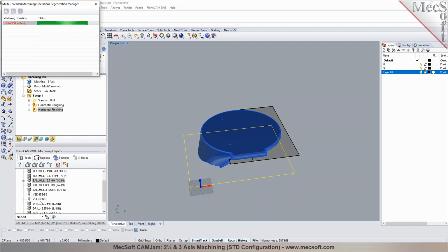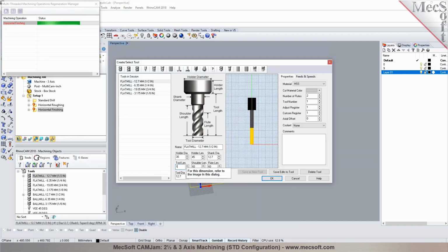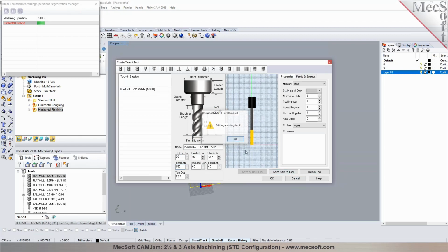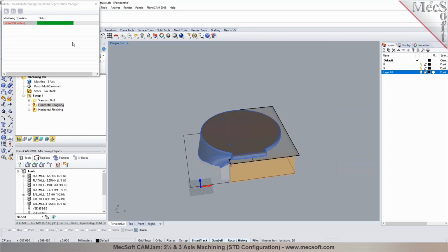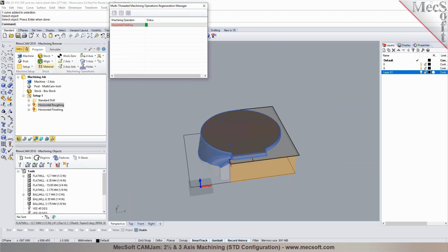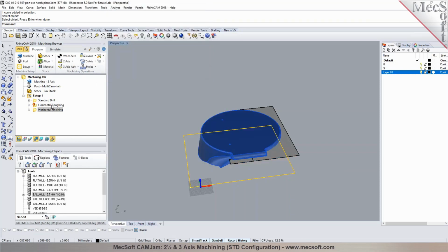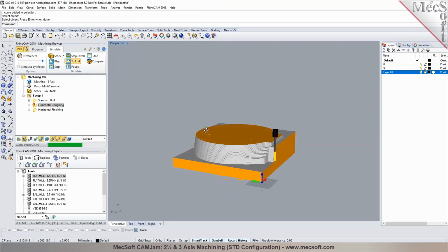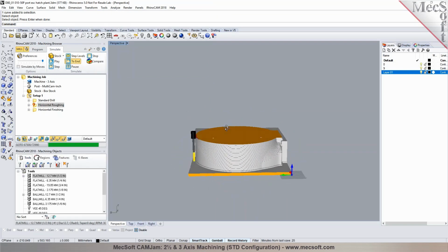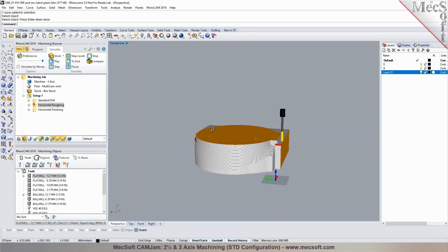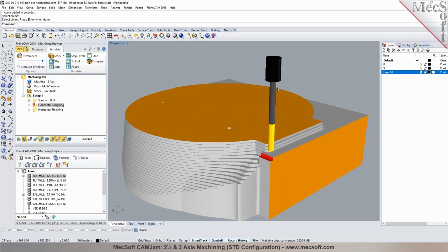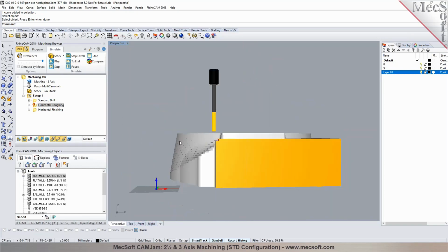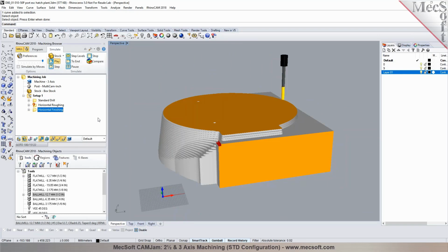Now if I go back in here and change the length for the first operation I use, I'll make this 150, and hopefully that'll work okay on this operation in here, the first one. So now the length of the tool, it's good for me to know, and it's good for the machine to know, so I can, for instance, detect when it has a collision. But in terms of the actual real dimensions, that's really determined by the operator on the machine. Right, the distance from the tip to the spindle face, or the collet face that we would call it. Yeah, exactly. It's really determined by.